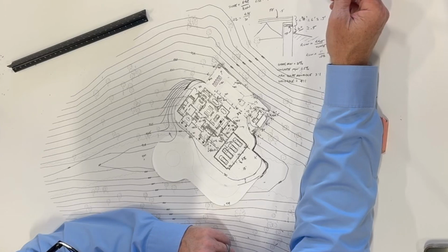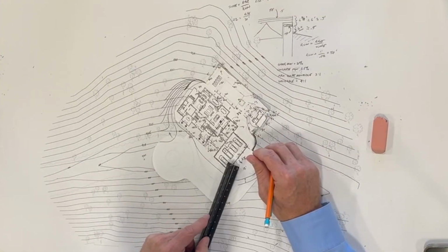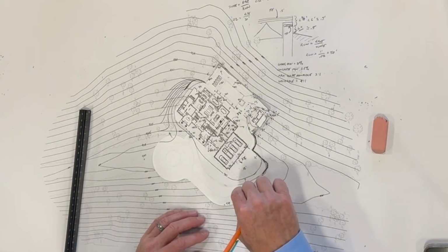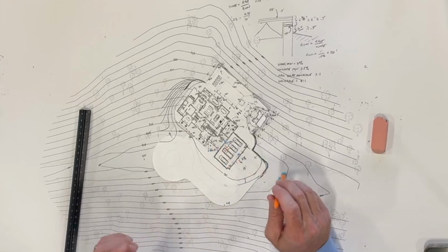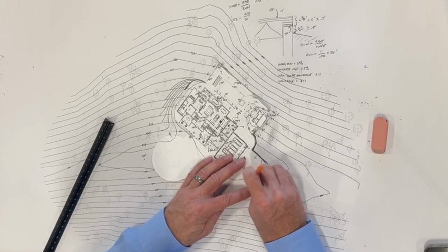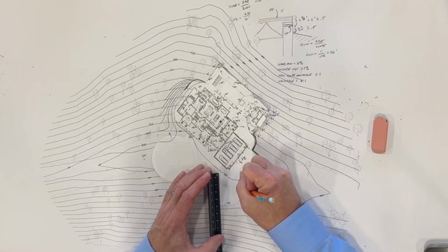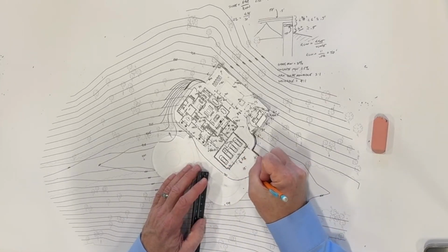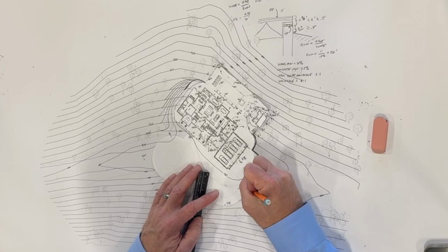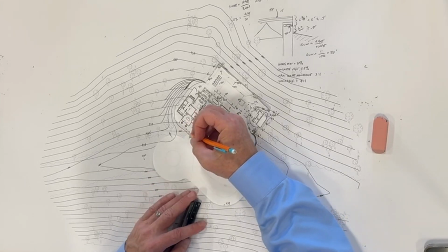So Christian, why don't you give us a 1 foot divided by 0.08? So what that means is these lines, this is really where it comes into play, cannot be closer than 12.5 feet away from each other, or that means that the slope will be greater than 8%. So for this driveway, 12.5 is kind of out there a bit. It's like here. So really that's the closest we can put those lines. That's the closest it can be, which means this line will then come over here into the retaining wall. And then that's an 8% slope.